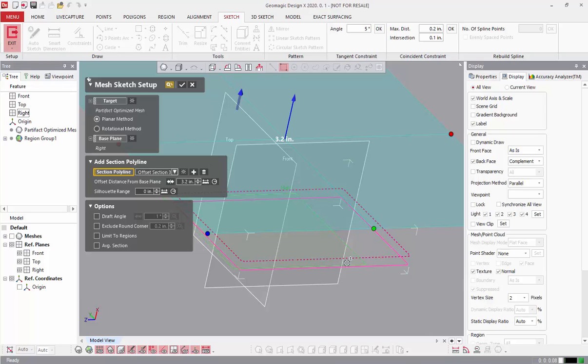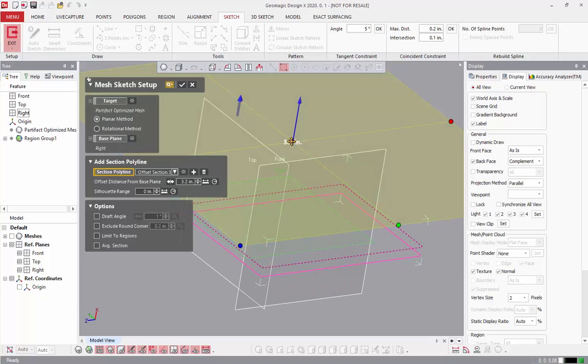There's a dashed line, which is that cross section projected onto my sketch plane, because remember that we're always creating a sketch on that plane that we've selected here, this base plane, my right plane. And if I'm adding another section here, if I drag this cross section down, I'll get another dashed section, which is the projection of this new cross section offset from the base plane there.